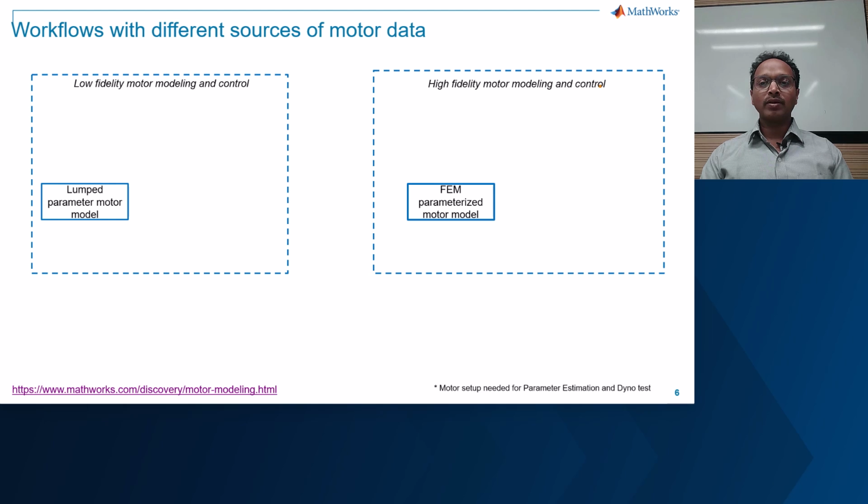Now for characterizing the motor, we could choose to work with lumped parameters or nonlinear parameters. What do we mean by nonlinear parameters for a motor? When a motor is operated within the linear region with small values for currents, it will have no change in the characteristics such as inductances. Only when the motor's iron core saturates, the resulting inductance reduces and hence the characteristics depend on the operating currents ID and IQ. At high load conditions or high speed conditions, one or both of D and Q axis currents may have high values, enough to saturate the soft magnetic core in the stator.